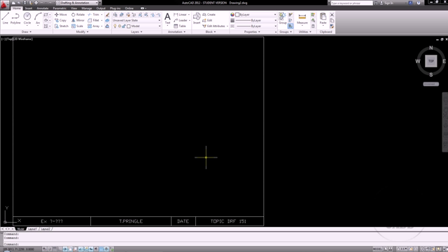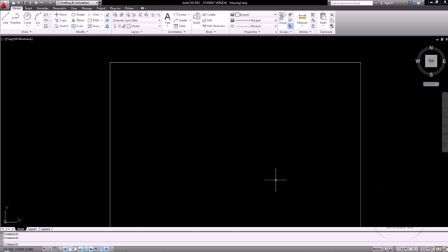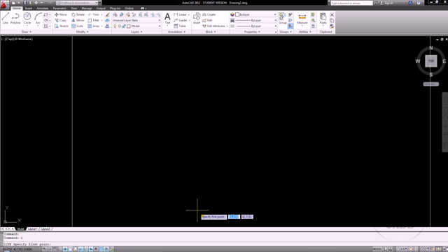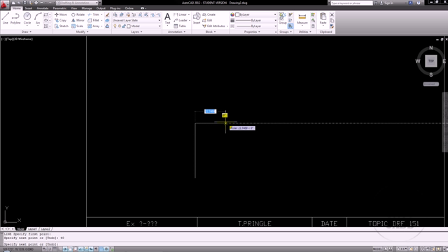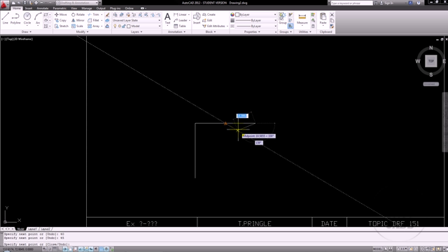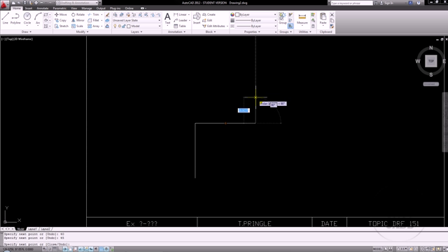For exercise 5-22, I've already started a metric file, and to do this I'm just going to begin by drawing the front view. Now there's a little bit of math that we're going to have to do as we go along here, just to make things a little bit easier to follow. But what I want to do first is draw a line straight up 40. My next segment is going to come over here 45. Then that's going to go up 15,